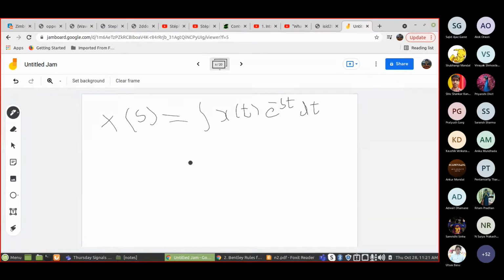If the signal is right-sided, for example, we have seen that if it is a complex exponential, you get something like this, with a positive. If the signal is right-sided, then you always have your ROC to be on the right of your pole. So this is our pole, for example, in this situation.